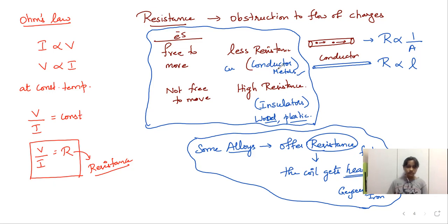So, conductor's resistance actually depends upon which material you are using. See, the same thickness, the same length I can use, but I'm going to use a copper in one and wood in another. The resistance depends upon what the material, right? Yes. So the material, the property associated with a given material, it is called as resistivity. Resistivity is denoted as rho, and the R value is directly proportional to resistivity.